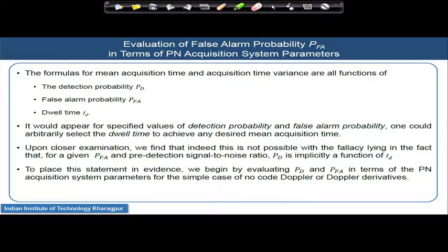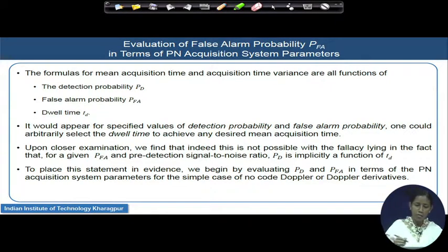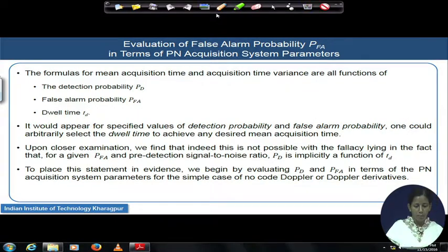The performance measure largely involves the detection probability, which basically tells how many times you are successfully achieving the synchronization, I mean, the threshold is properly crossing the level, and hence you declare that you have acquired the synchronization. It also involves how many times you have missed and how many times you have given a false detection.